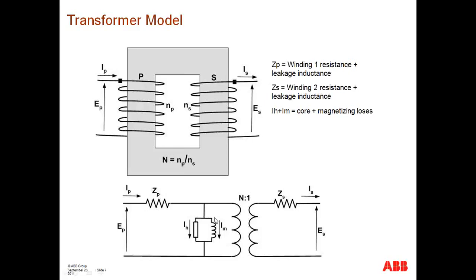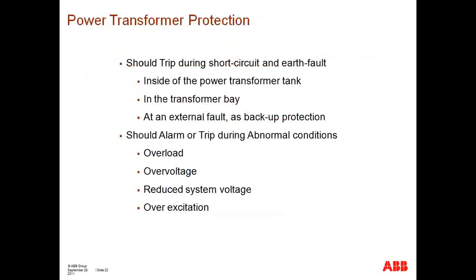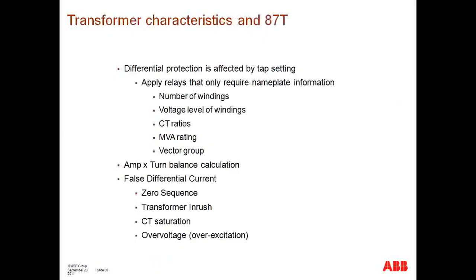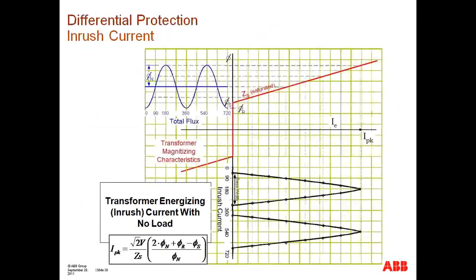There are different degrees at which this phenomenon produces higher or lesser inrush currents. The point on wave switching, meaning whether the transformer is being energized at peak voltage or at the zero crossing of the voltage waveform, has a lot to do with it. The X over R ratio, the SIR ratio, and so on. And remnant flux inside of the transformer. Those are all things that need to be taken into consideration that will result in more inrush current or less inrush current.